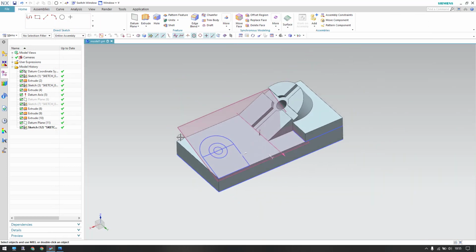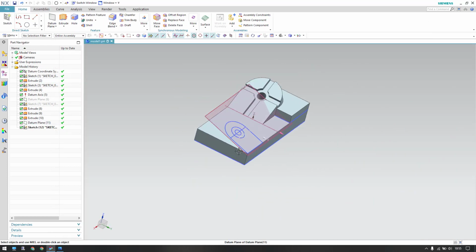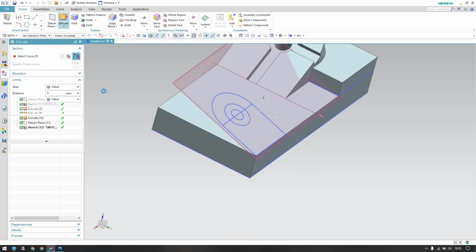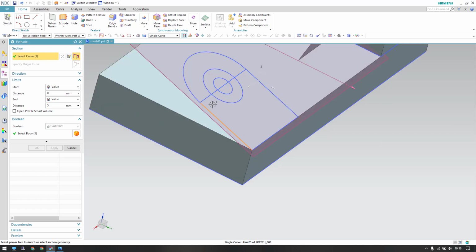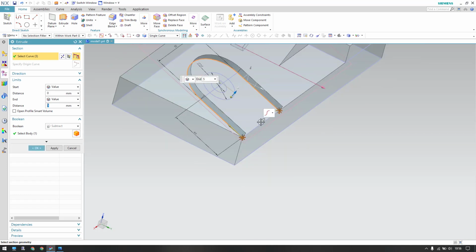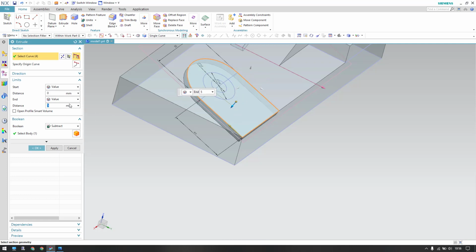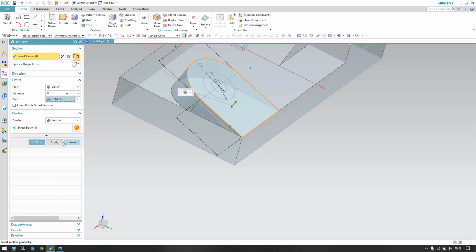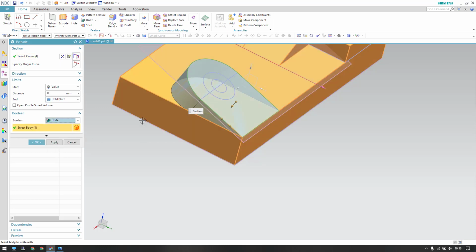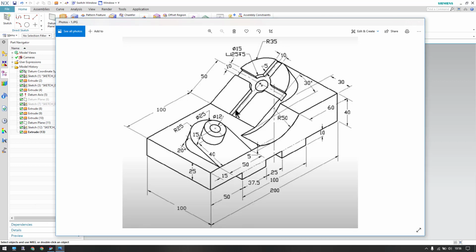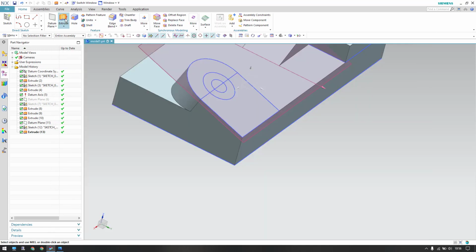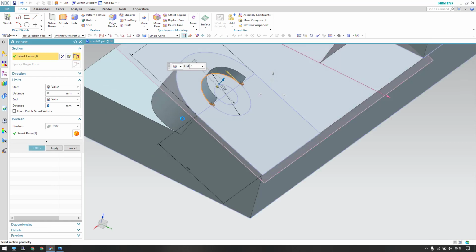Now in the same way, I'm going to select first the outer shell we have. Single curve and stop at intersection. These are my single curves that I'm going to select. It should be in the opposite direction, and we need to select until next. It is not a subtract, it should be united with the body. Let's click OK. Now as you can see here, there is a width of 15 mm, which is for the diameter of 25. So let us give 15 mm for this circle.